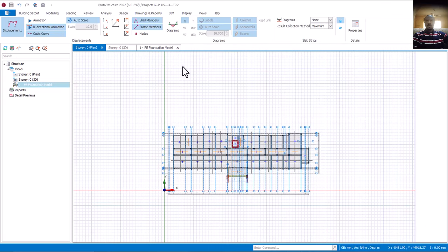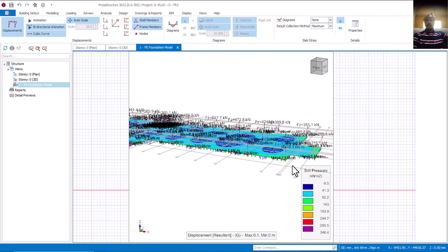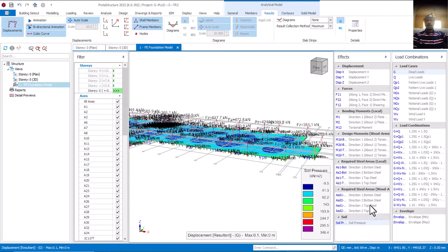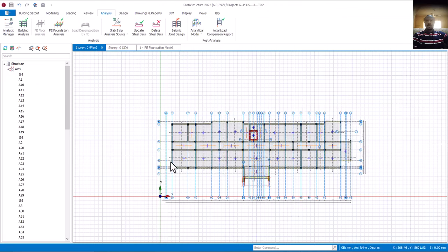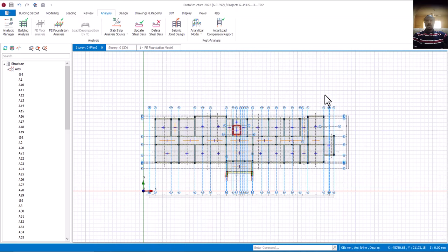So if you notice, you now discover that at this point, when we are loading it, at this place there was no error appearing here, which means that our slab thickness is very okay, isn't it? So that is fine. Okay, and if there's anything, we will see it now. So at this point, I will click here, outside here. I'm at story 0, and I've drawn my slab strip. I'll come here, right click and click on update steel. Can you see update steel?